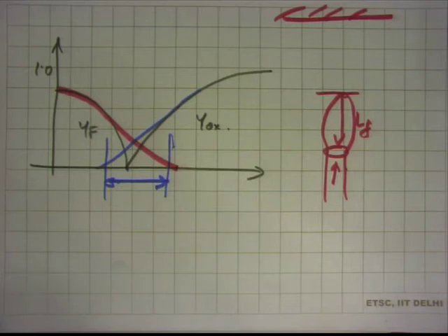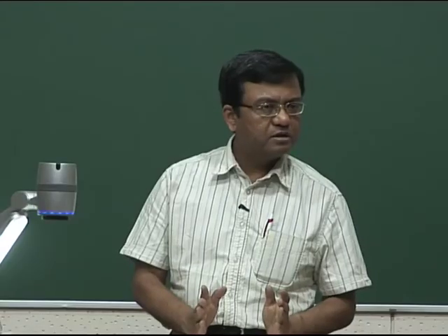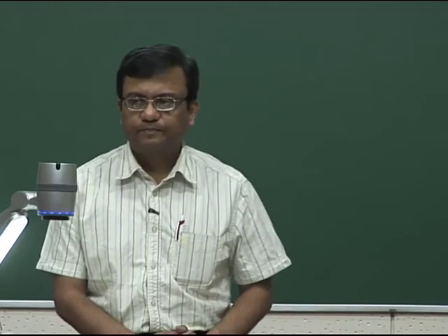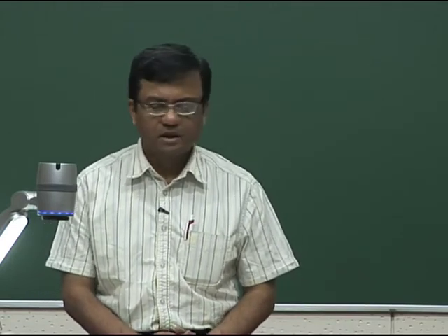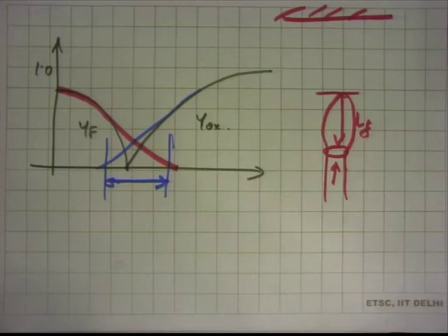Now, contrasting this with laminar premixed flames, in laminar premixed flames we could actually derive laminar burning velocity. That was more of an objective for us, because that was a fundamental property of premixed flames, and we saw that when we went to turbulent premixed flames, there also we used laminar burning velocity. St equal to SL plus something. Remember that? Okay. So getting laminar burning velocity was important when talking about premixed flames, and we did primarily laminar premixed flames. But what about laminar non-premixed flames? Is there a burning velocity?